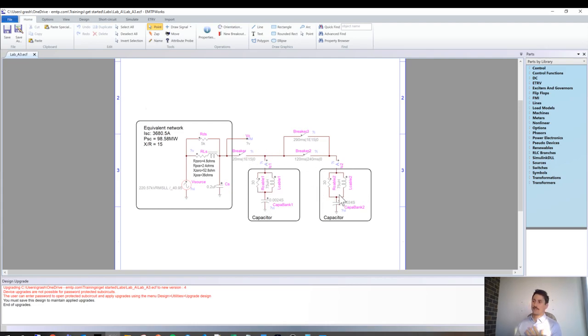It's almost mathematical: if you take two capacitors and connect them to one another, and they don't have the same voltage, you have an infinite current going from one to another to put them at the same voltage instantaneously. In reality, you have the impedance of the cable in between, which is very small. So you will not have an infinite current, but you will have a very high current with a very high frequency content due to the very small inductance. We are going to see that.